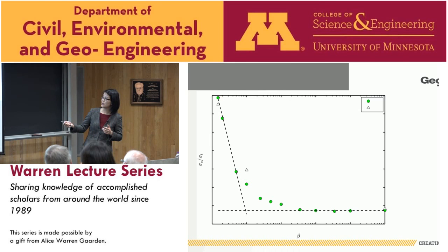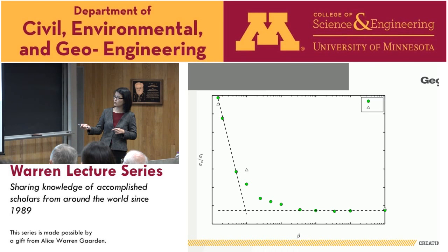If you put in a very stiff unloading path, the unloading is governed by the neighborhood, by the system. Therefore, your softening path, or even when you go to the brittle mode, your unloading is not following the softening path you prescribed, it is following the behavior of the system. And therefore, whatever you put in is ineffective.